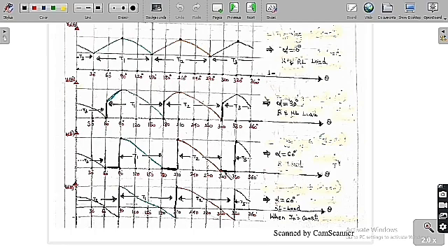You can see some gaps here, zero voltage, or discontinuous mode, which we get only for R load whenever alpha is greater than 30. So remember, whenever alpha is greater than 30 degrees, for pure resistive load only, there will be a discontinuous mode of output voltage. Whereas if you take RL load, same thing here, for alpha equal to 60 degrees, same case as the previous one.